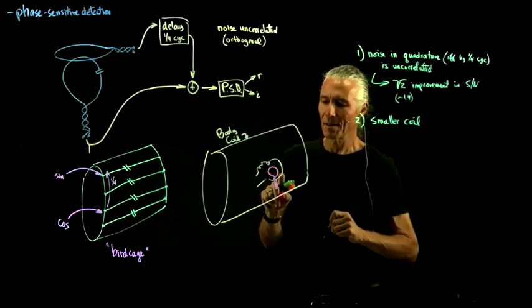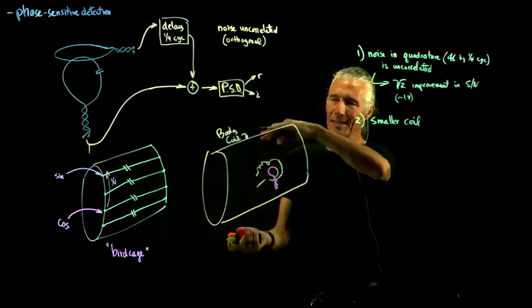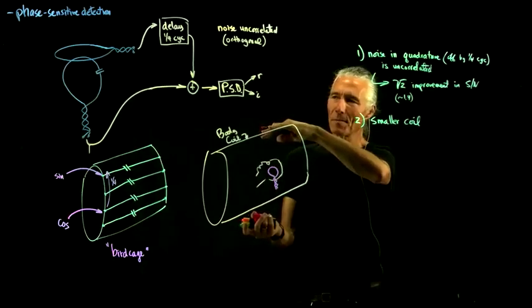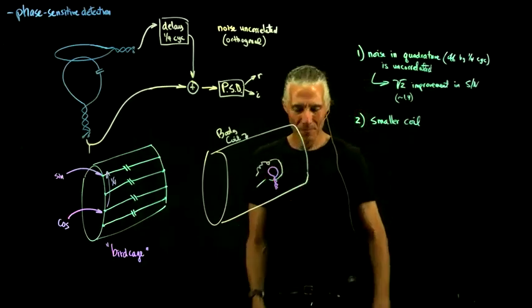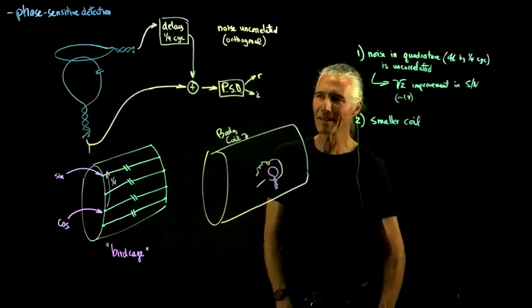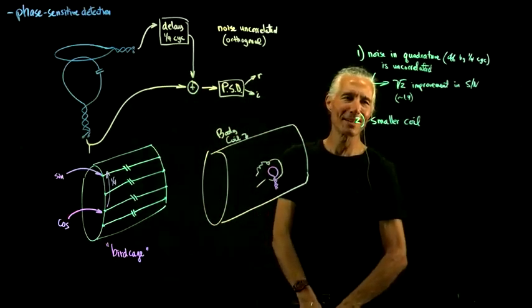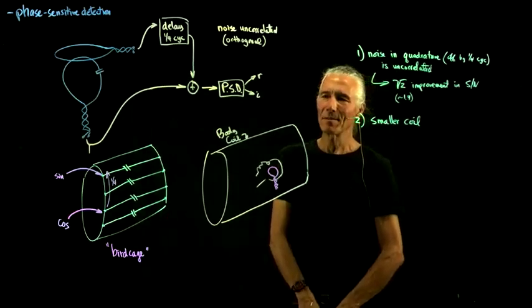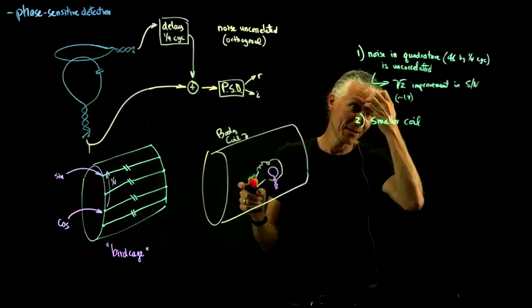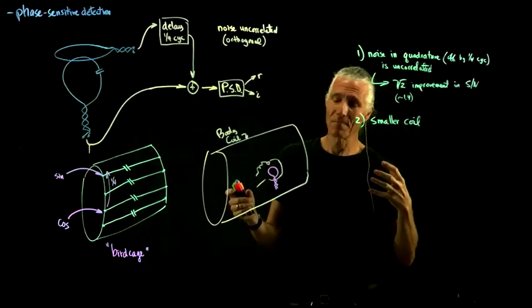Well, some radio waves came out of your head, and then you got this big antenna to pick them up, and it does a great job of picking them up. So if I want to test, did somebody leave a smartwatch somewhere in the MRI magnet? It's generating a bunch of radio wave noise inside the MRI. I would use the body coil to try to diagnose that, because it's a big antenna.